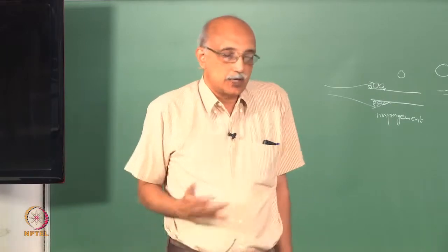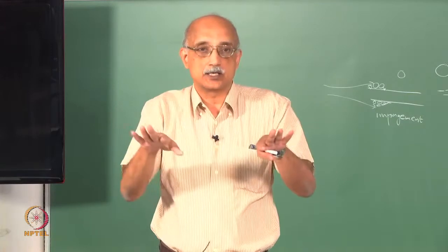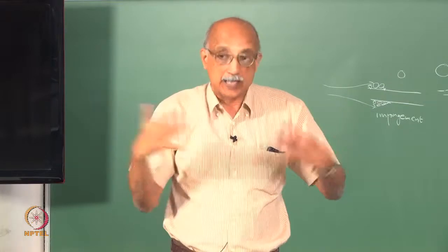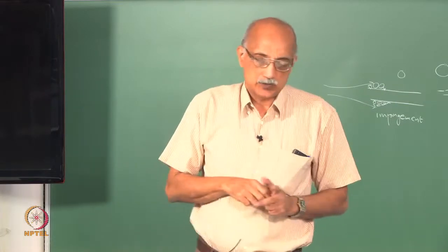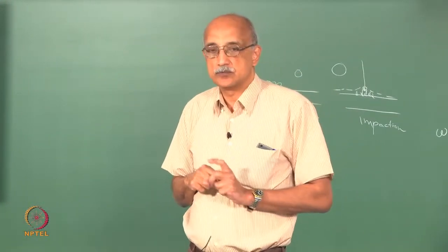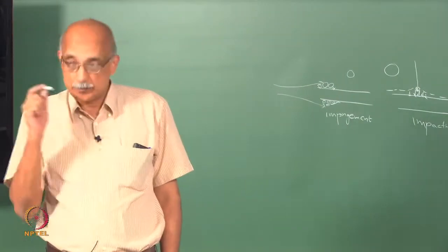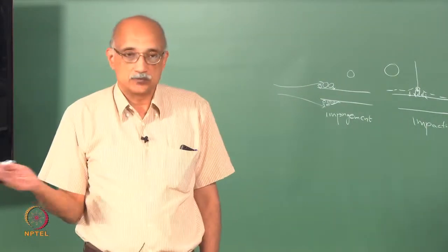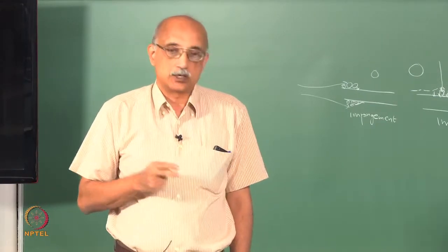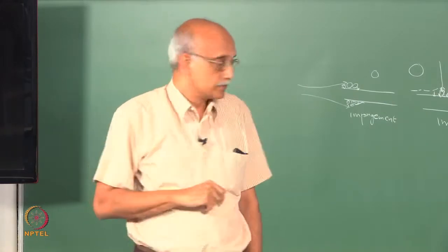So, if you are trying to do manufacturing in this type of a cleanroom, you will make sure that you do the manufacturing only in areas where you know that the airflow is controlled and operating as per your requirements. So, in a cleanroom, you kind of know how the airflow is happening, and therefore, you can choose to do your sampling pretty much anywhere in the cleanroom, and you will be fairly representative of the entire room. And you can also use filtration as a mechanism to control how clean the room is.